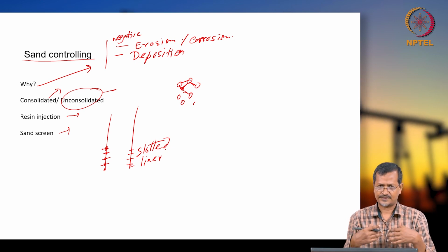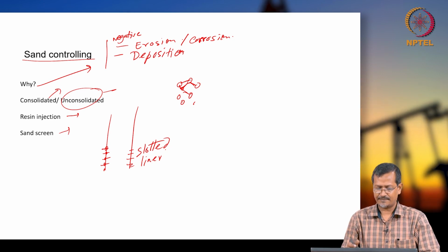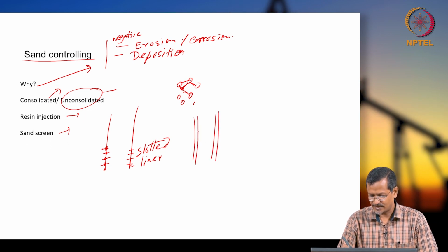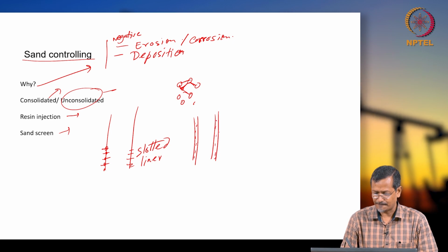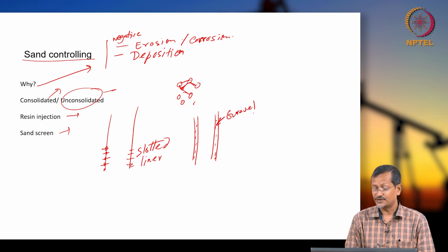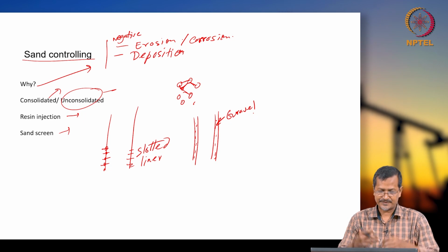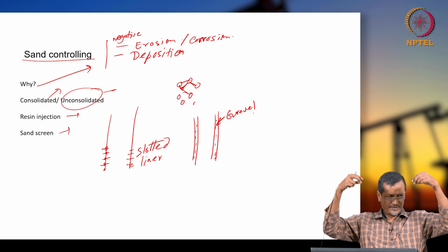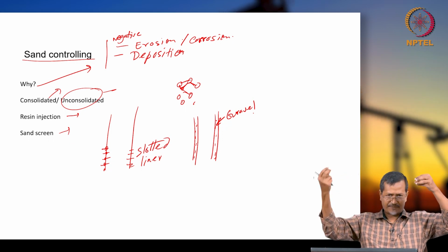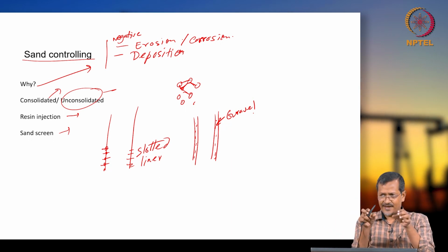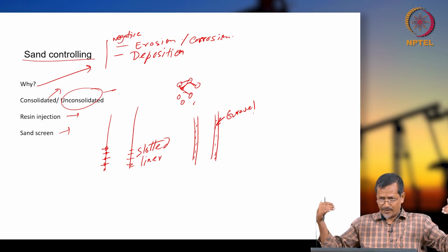So then the engineers thought, let's make some different type. So they made different layers. One layer is here, one layer is here. In between they put lots of gravel. So the gravel packs. One pipe is there, put inside another pipe, make lots of holes in the pipe. In between the pipes, you put lots of gravel or sand type of thing, so that you are creating a porous pipe actually, a 2-layer porous pipe, and your sand movement will be lower.